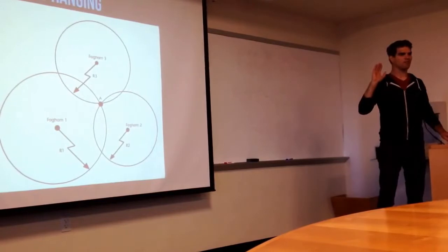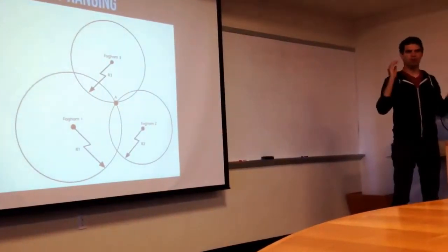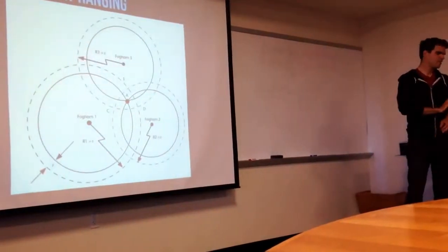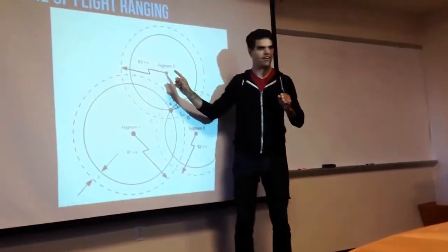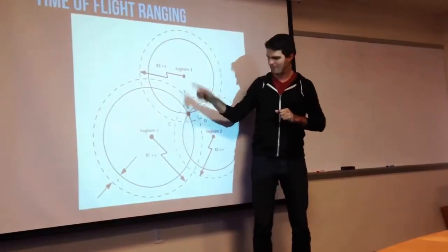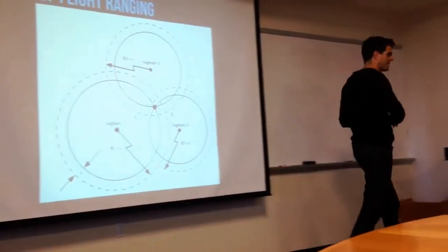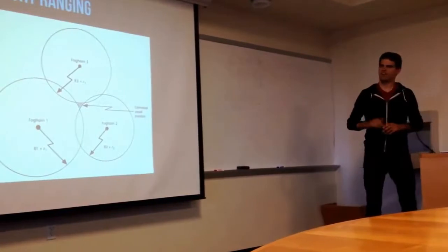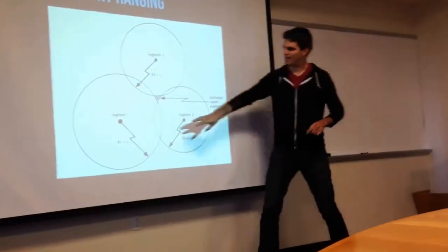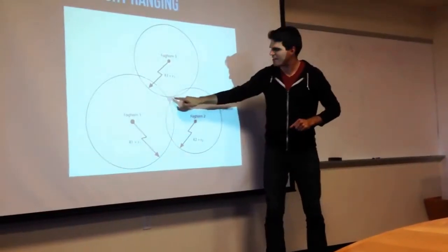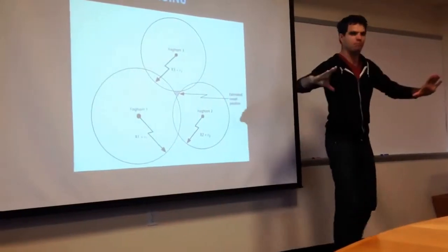And of course, with all those assumptions, that means we will introduce some error. We will not be able to do a perfect job for all of those. And what that means is that we actually won't be able to calculate a perfect range from us to our base stations. We will calculate some range plus some epsilon error. Okay? And what that means is that our circles won't perfectly intersect. We'll have some area and say, well, okay, there's some error in our ranging measurements, so there's some error, but we're somewhere over here, right? And the worse that error gets, the bigger my spot is.